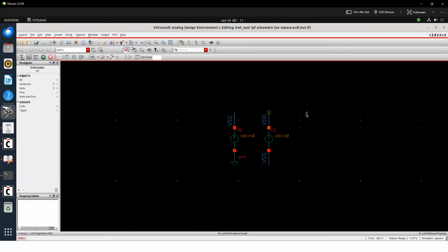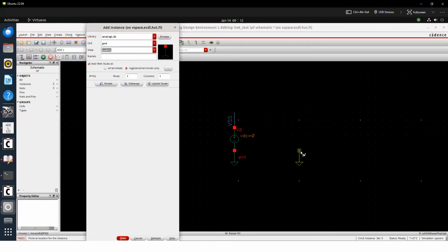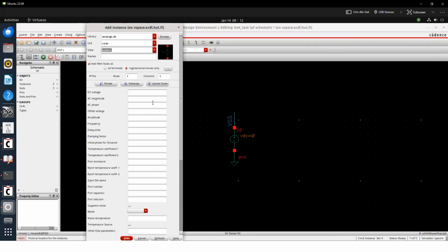But this is the typical case when we want to set up our circuit simulation for the transistor level, but we are not considering this one anymore because we are just simulating an RC circuit. So let's put a V source here to run some AC analysis. So we can set AC magnitude as 1. So here it says that it has 1 volt, right?